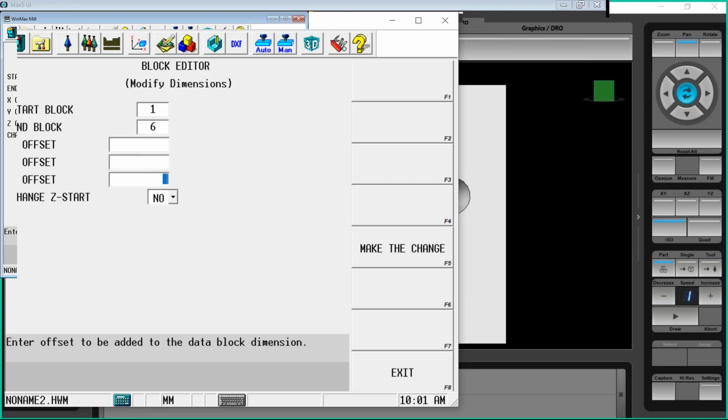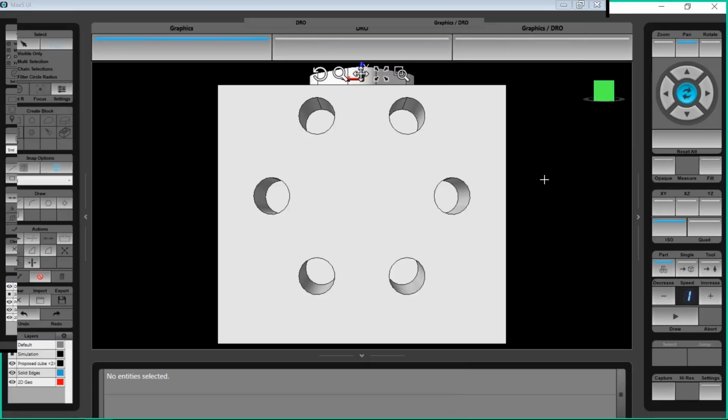The other would be a spiral, like a parametric offset. It would take the boundary of that surface and spiral either inward or outward based on your selection. Are we still restricted to ball nose cutters? Right now, we are restricted to ball nose. However, there will be the availability to use bull nose if you have enough of an angle on your part.